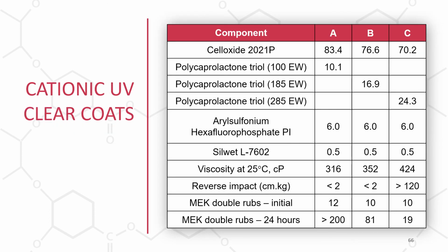Here we have a cationic UV clear coat that uses a range of polycaprolactone triols as the polyols, at different equivalent weights, in three formulations.